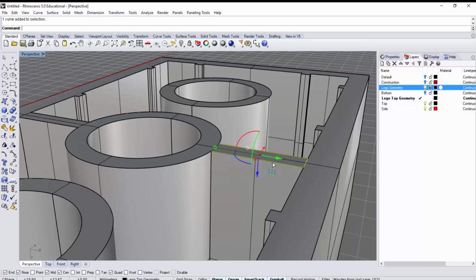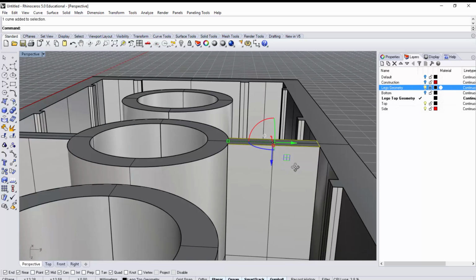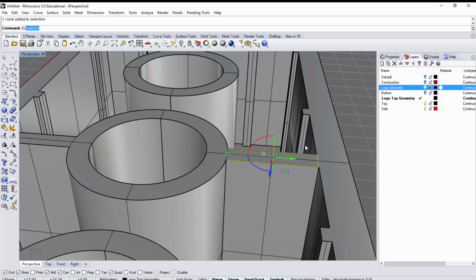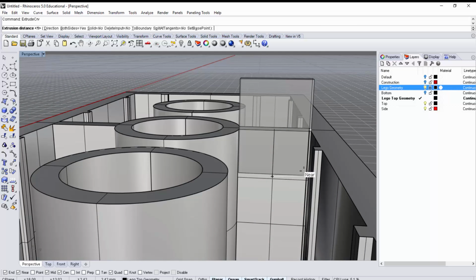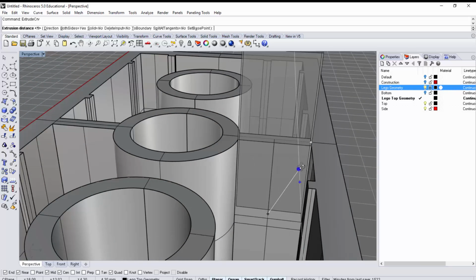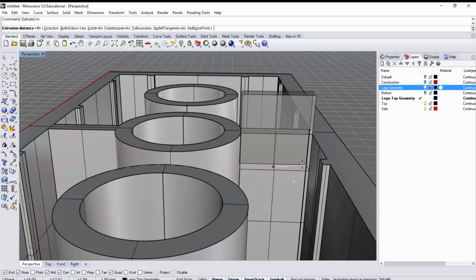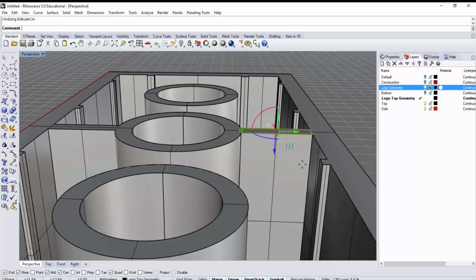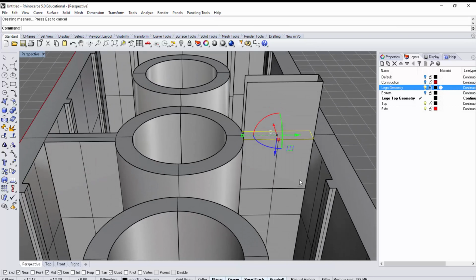What I'm going to do is make a surface to Boolean difference into this brick. So I'm going to try it on this side first. I'm going to extrude this curve, and I want to go down, I believe, one. We'll do both sides because we want to be extending beyond the geometry that we want to cut. Let me see what one's going to look like. That's not far enough. So let's see what 3 is like. That feels a little more accurate.